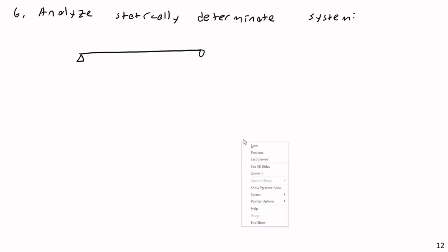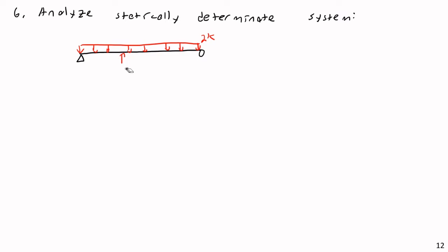So what I mean by this is what your beam now becomes. We can analyze it as a simply supported beam with a distributed load of 2 kips per foot, and instead of a reaction, an upward load of 27.683 kips, the reaction that we found using the force method. And we'll have 12 feet and 10 feet here. And then we'd have an AY and a CY.